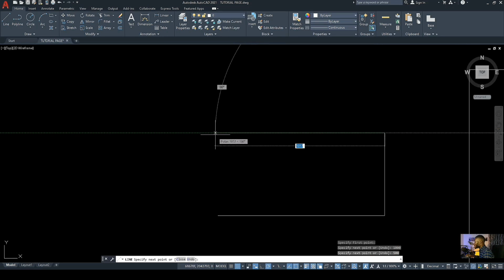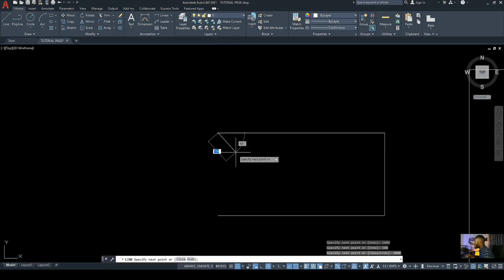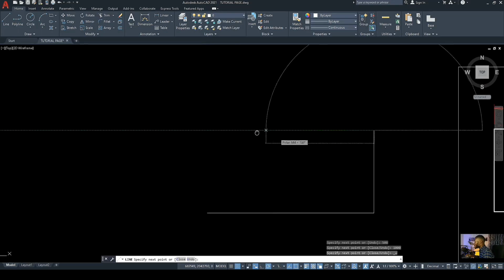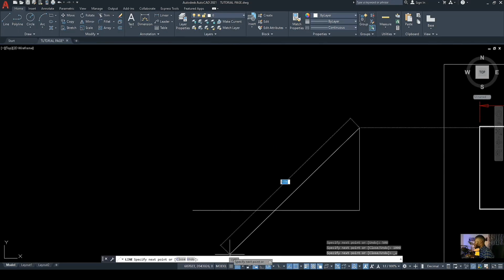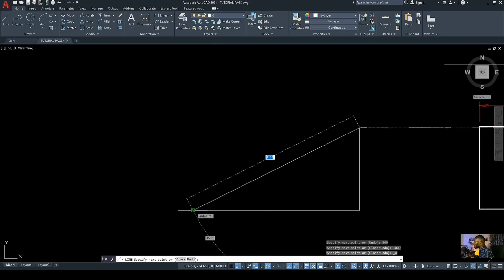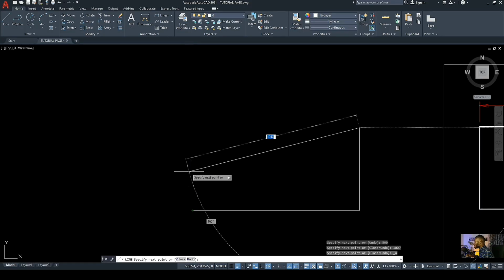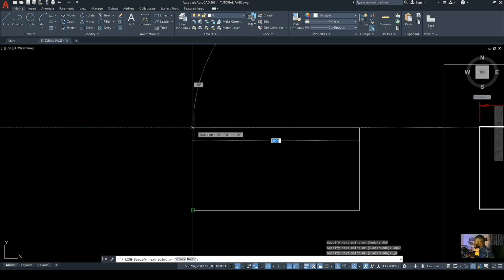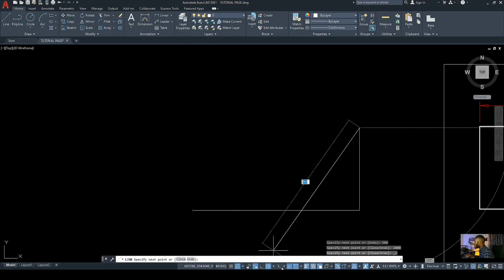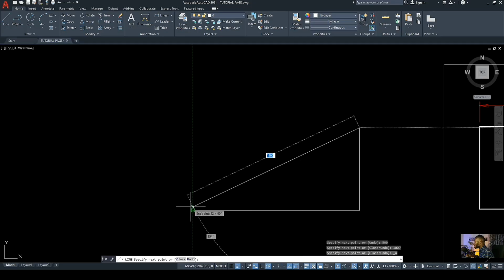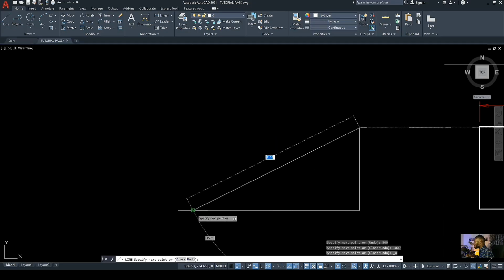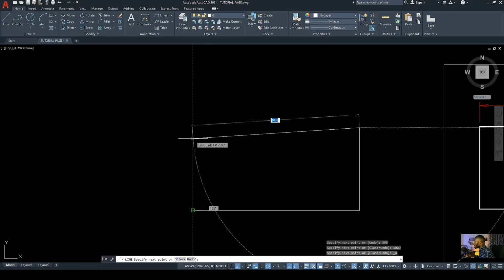We can type in the value 1000 millimeter, enter, or you can just use the help of the snap tool, which is this. You can snap from this angle, then project it up. You see your snap grid line, and your show snapping reference line, which is showing this green, more like a construction line guiding your path to the actual destination.